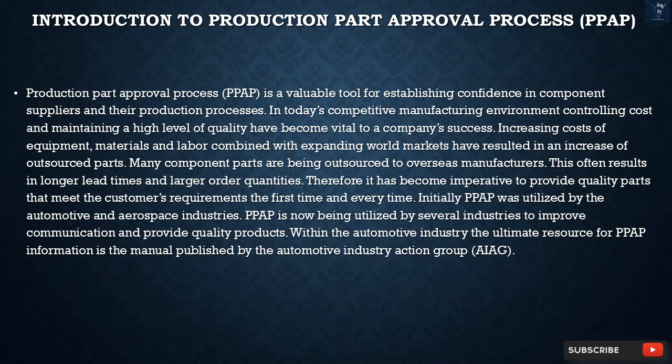Many component parts are being outsourced to overseas manufacturers. This often results in longer lead times and larger order quantities. Therefore, it has become imperative to provide quality parts that meet the customer's requirements the first time and every time. Initially, PPAP was utilized by the automotive and aerospace industries. PPAP is now being utilized by several industries to improve communication and provide quality products. Within the automotive industry, the ultimate resource for PPAP information is the manual published by the Automotive Industry Action Group, AIAG.